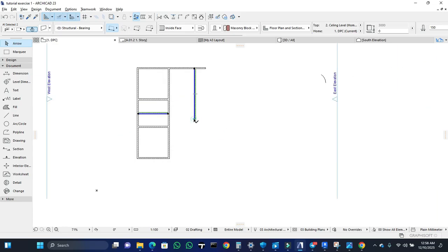So if this was longer and I clicked on intersect, it was going to intersect this way instead of that way. But now that I took it closer, if I click intersect, it's going to intersect in the direction of the longer wall. So I hope that explains itself.